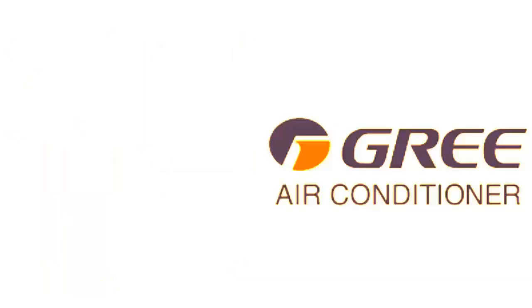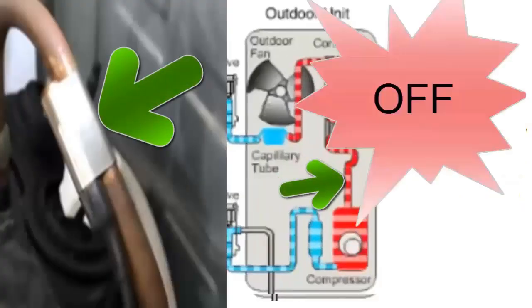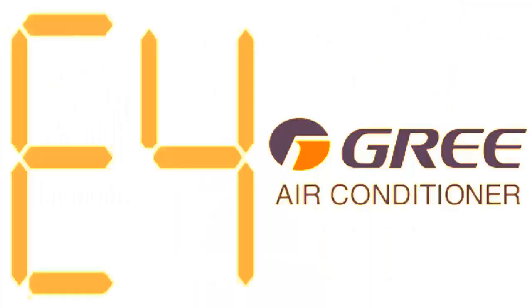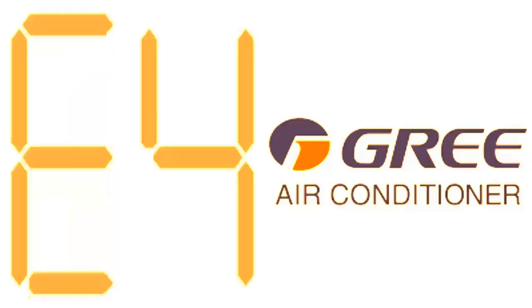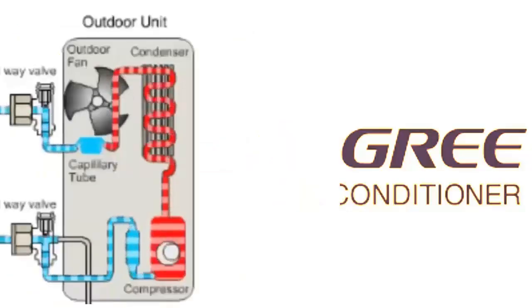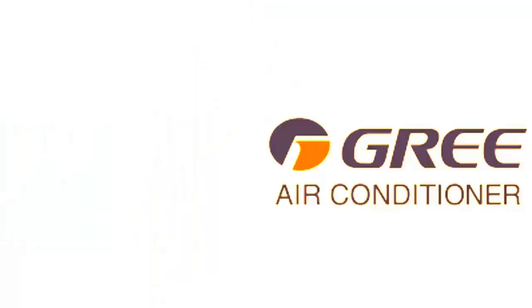Error code E4 indicates high discharge temperature protection of the compressor. This occurs when the compressor's discharge temperature exceeds the safe limit, possibly due to overheating, low refrigerant levels, or ventilation system problems. As a result of error E4, in cooling mode, the compressor and outdoor fan stop while the indoor fan continues to operate. In heating mode, the entire unit shuts down. If this protection activates more than 6 times, the unit will not recover automatically and will require a manual reset.